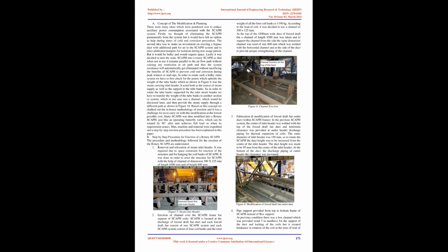Number of tubes, 42 in one coil. Inlet header size, 150 mm. Outlet header size, 50 mm. SCAF weight, 1.2 MT. Material of construction: tubes and other associated systems are made of carbon steel, SA210 grade, having thermal conductivity around 45 to 50 watt per meter Kelvin.